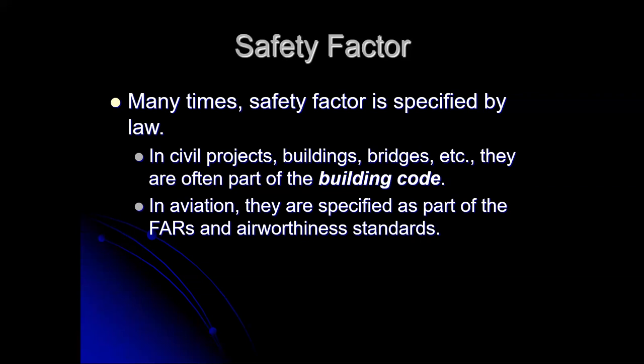If we are designing a tank, for example, a propane tank, typically a safety factor of 2 minimum is what we'd use for systems that are on the ground. But if that's a system that's going to fly or go into space, we generally back that off to about a 1.5 to maybe even down to 1.2 as our safety factor.